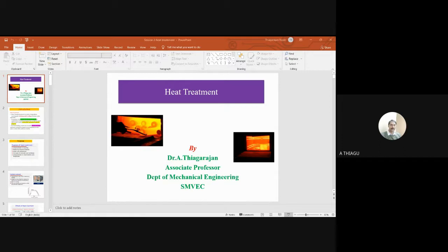Preheat means the sample should be allowed to heat to 300 to 400 degrees. And here in the carburizing zone the temperature will be around 550 degrees centigrade, and normally 2 to 10 hours will be required to complete the process. Here a case depth of 0.5 mm is possible, noted. Is it right? Suitable applications are gears, nuts and bolts. These are quite interesting applications. The only thing is carburizing gas of propane and ammonia gas of NH3 will be used. The rest of the things are very common.